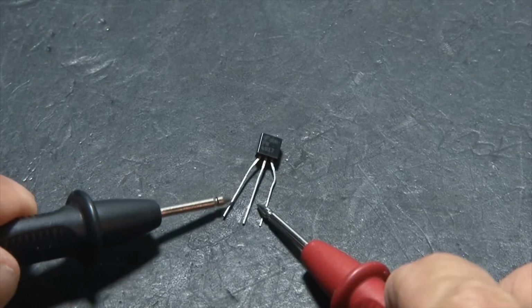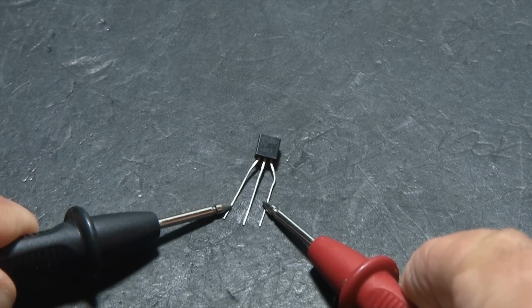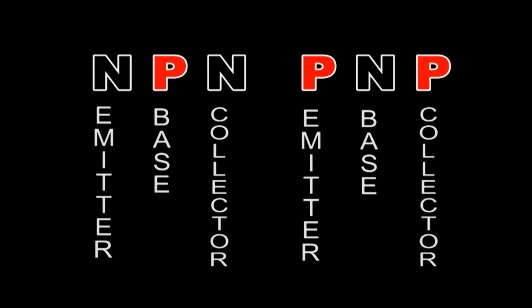And finally, we'll measure between the emitter and the collector. You should not get a reading on your multimeter. If you do, this transistor is likely bad. Here's an easy way to remember it. NPN stands for negative, positive, and negative. And PNP stands for positive, negative, and positive, as to where you would put your leads for your multimeter.